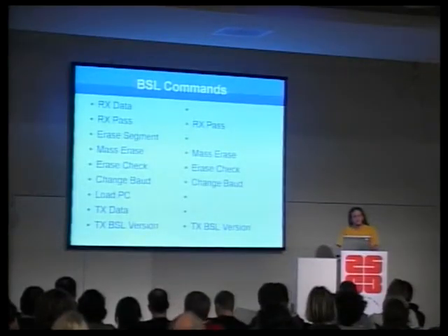Also worth mentioning is that the change baud rate command doesn't actually change the baud rate. It actually changes the clock rate. We'll get into how it figures out serial timing. But in some versions, you can change the baud rate to something very high, actually setting the clock very high. And then you can brute force passwords faster. Conveniently, those are the ones that my timing attack does not work against.